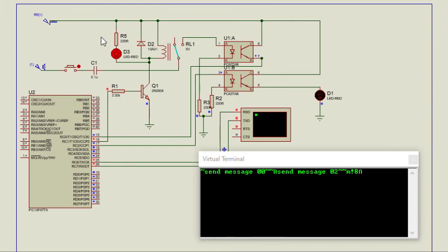The system will automatically pick up by making a closed circuit connecting the output to the ground. The LED D1 is an indication of that. The system will play a greeting vocal message from the SD card. The LED D3 also indicates that the relay 1 is in the second position, which means the system is accepting the inputs made by the user.